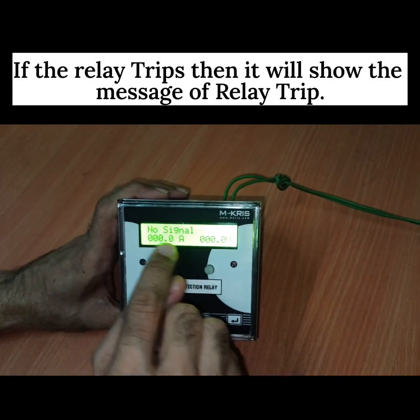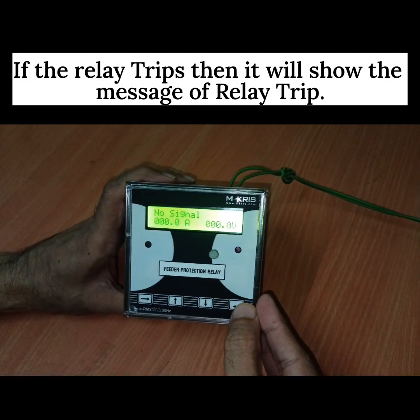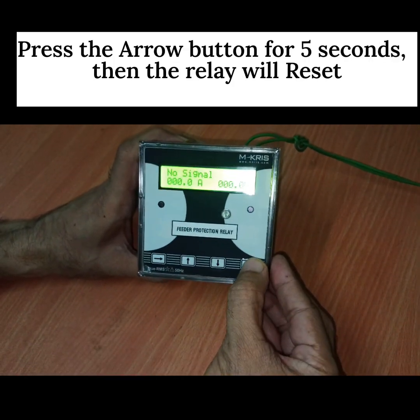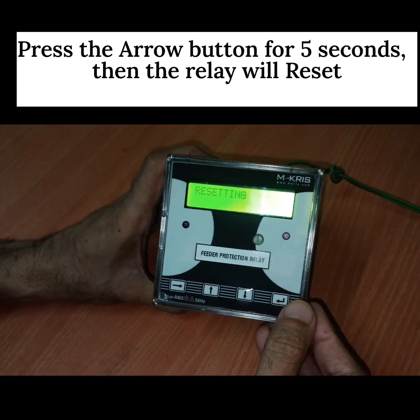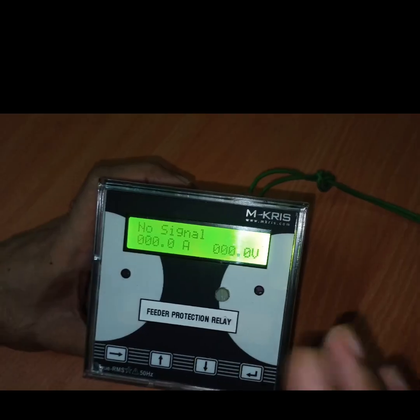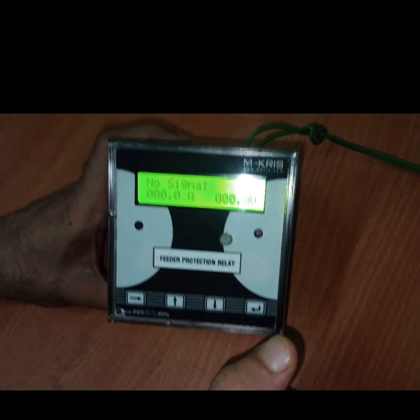And when the relay trips, it will show a message here, relay tripped. The relay can be reset by pressing this button. And even during the running of the relay, if we keep this button pressed for 5 seconds, the relay will reset. Reset done. And as we said, when the relay trips on a fault, simply pressing it once, the relay will be reset.